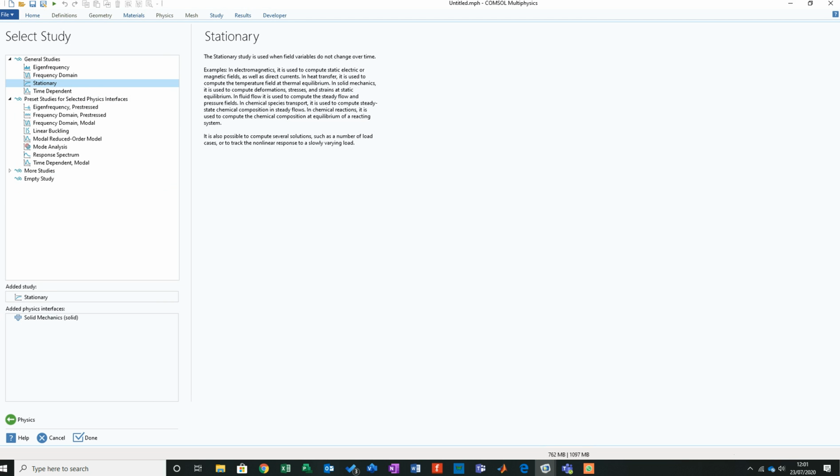Now what we're going to do in this is we're going to do something really sophisticated. We're going to use a parametric study to systematically move it, and then we can look at what's occurring throughout that rise of the stress. See if there's anything there. I mean, in this case, there isn't much, but it allows you to see the idea of having variant sweeps without even having to go into time-dependent responses. Time dependency is something else. We are going to do that because the beauty is with YouTube, the beauty is with what we're doing here, we can go crazy and look at different options. So let's go to done.